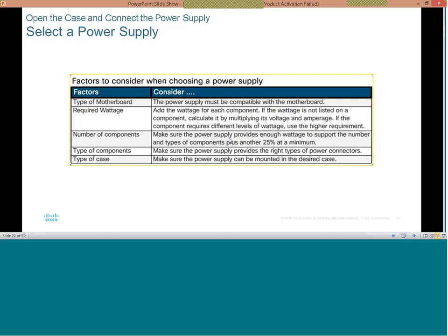In such situations, you have to be careful before you power on the desktops or use your laptops, because the voltage coming into the system might be under delivered. So you need to use your multimeter to check if what is coming out is enough to power the system. You don't just put the system at risk by using low voltage.